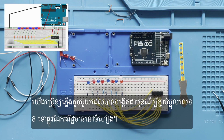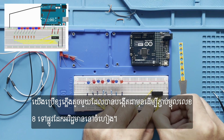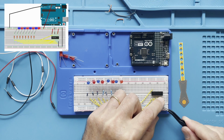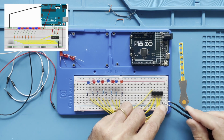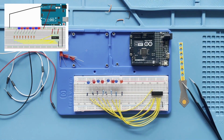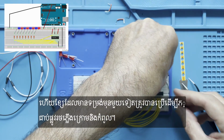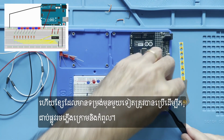We use one of the small preformed wires to connect pin 8 to the negative rail on the side. And another preformed wire is used to connect the bottom and top ground rails.